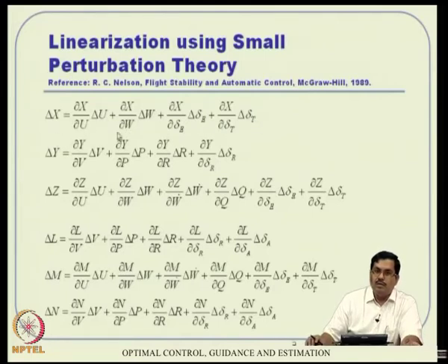Okay, and this series does not stop actually. Suppose somebody wants to write other functionalities, then they can still write it. But as far as perturbation in delta x is concerned, remember this delta x is the aerodynamic force in body x direction. This aerodynamic force can be a function of u, a function of delta w, a function of delta e, a function of delta thrust, all sorts of things. And this series can be expanded also. But these are the major components.